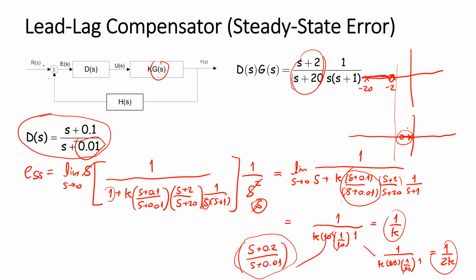So the effect of this one will be around here. It seems like we want to add a PI controller. We want to have 1 per S to show the pole here, but we cannot exactly do it. So we select the lag compensator instead.